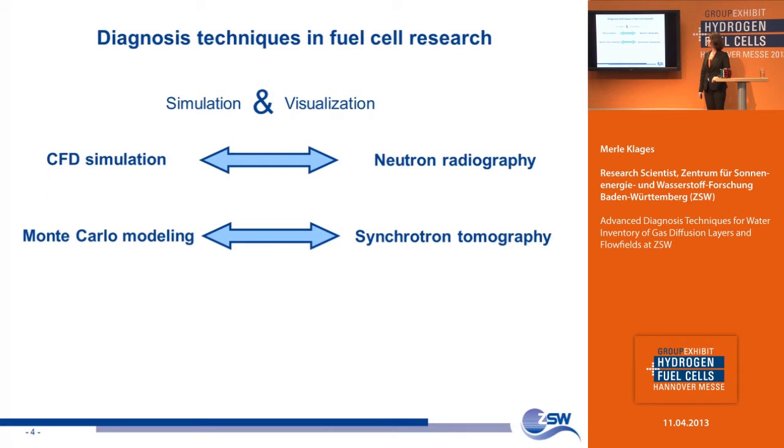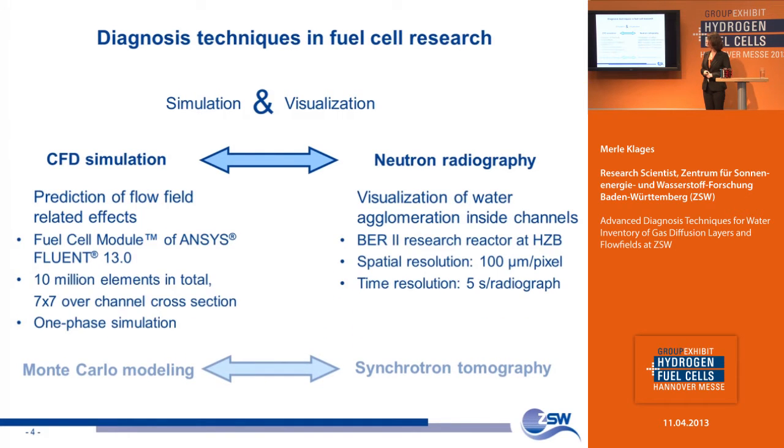I divided my presentation into two main topics: the combination of CFD and neutron radiography, and the combination of modeling with Monte Carlo and synchrotron tomography. Let's look at the first one. Basically, we simulated a fuel cell at particular operating conditions, and we visualized the same fuel cell components with neutron radiography to see where the water actually accumulates and how it is removed.